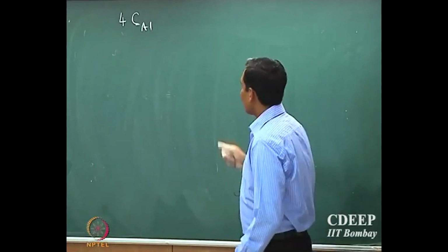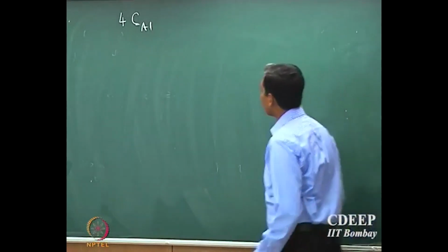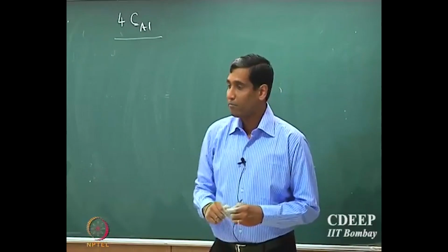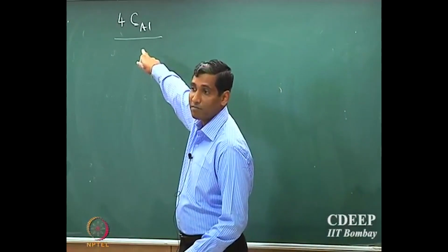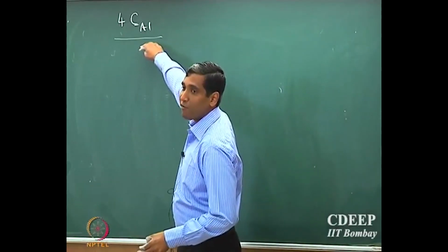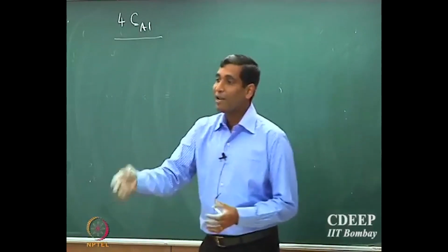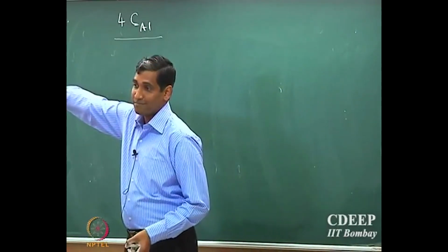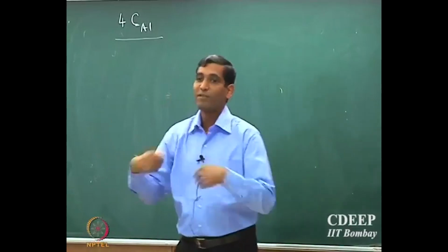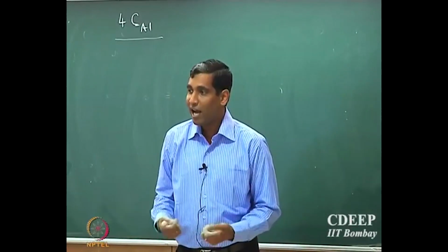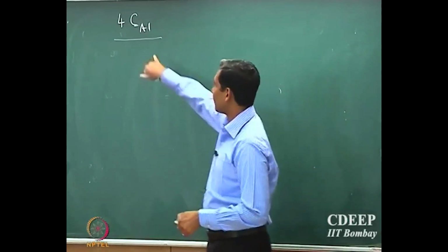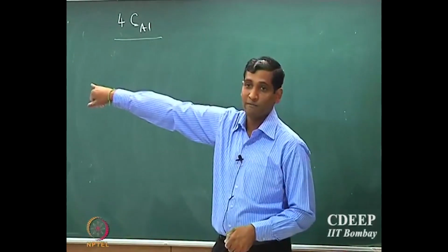Correct. So the first thing is that if you assume that the transport, the velocity effects because of the concentration change, is negligible, you can still have incompressible flow. If you have 4 times the species that is added, you can still tweak the velocity. You can have a higher velocity flow, you can have gradients, you can play with the gradients du by dx and du by dy and still maintain an incompressible fluid. So incompressible does not mean necessarily that the concentration does not affect the velocity.